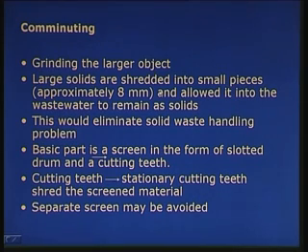Large solids are shredded, that means cut into small pieces, approximately 8 mm in size, and these small pieces are allowed to get into the wastewater to remain as solids. So, these large solids are cut into pieces and then they are allowed to go into the wastewater.